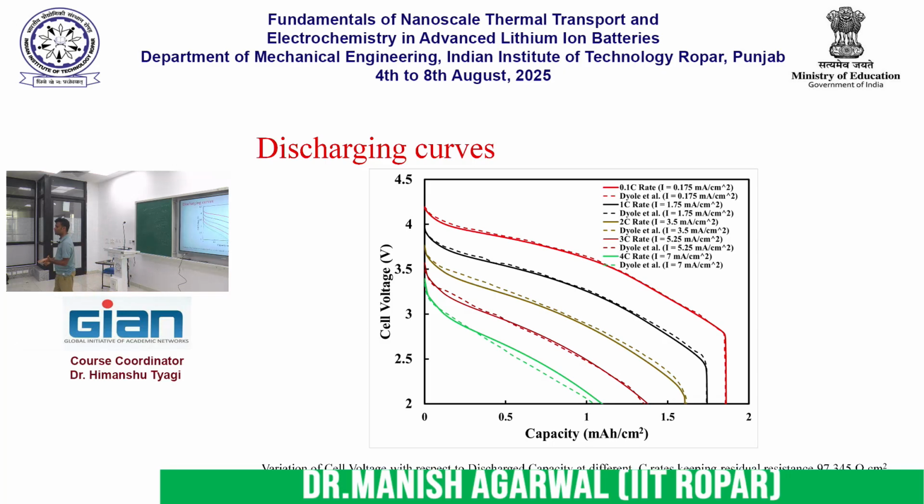So the charging or discharging rate considerably affects the battery performance. That's why you want to do the modeling. You want to understand how the battery is going to behave at different charging and discharging rates. What will be the voltage that I am going to draw? When I am designing the battery pack, I cannot just assume that I am going to get 4.2 volts, because as you can see, I don't get 4.2 volts. As soon as the battery starts discharging, my actual voltage drops, and that is fine, but the trickier part is that this actual voltage depends on the charging and discharging rate.